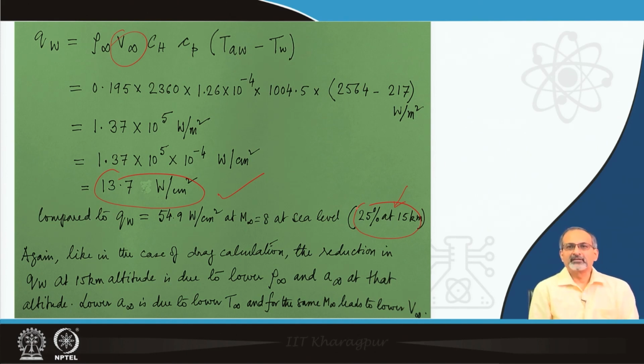However, we understood that very high temperatures are to be encountered at these kinds of hypersonic conditions, and there is no alternative out of that. Therefore, we need to understand what happens to the state of the air, or the working fluid, when it encounters high temperatures.